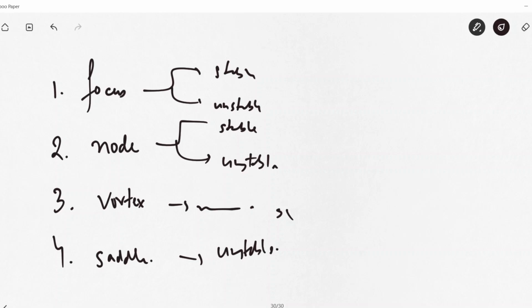Another equilibrium point is pi, 0 rather, which is not located at the origin, it is located at its own position. What we do in that case is shift this equilibrium point towards the origin by translating. Instead of using x1, we use x1 bar, where x1 bar equals x1 minus pi, and we obtain the state space in terms of x1 bar and x2 bar, so that the equilibrium point that was at pi, 0 is now shifted to the origin at 0, 0. These equilibrium points exhibit the property that x dot is equal to 0, and located at the origin. They are also known as the singular points of nonlinear systems.